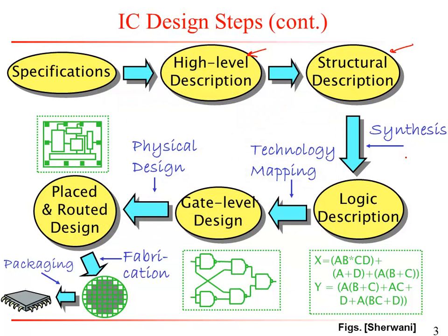Basically, questions of that sort. So you're going into more levels of detail. And then from the structural description, you go to logic description. The logic description now doesn't just say to use an adder, but it also says to use an XOR gate to add A_i, B_i, and the incoming carry to generate a sum at bit position i, and also to take the majority gate and find the carry out of the signal.